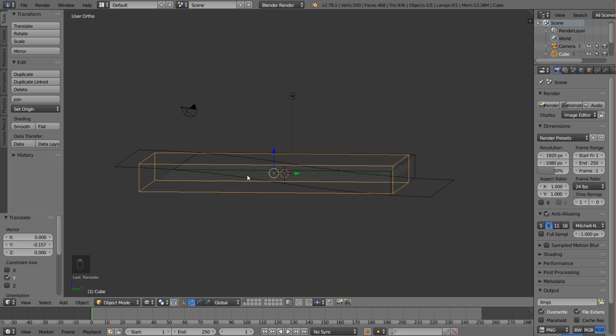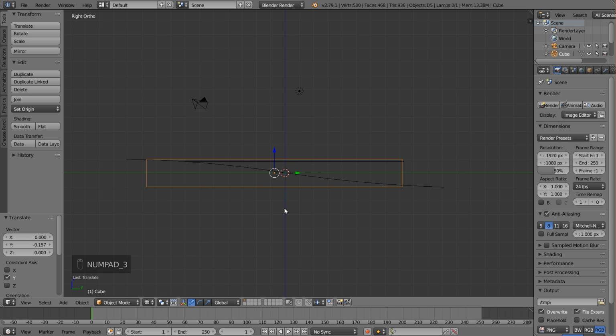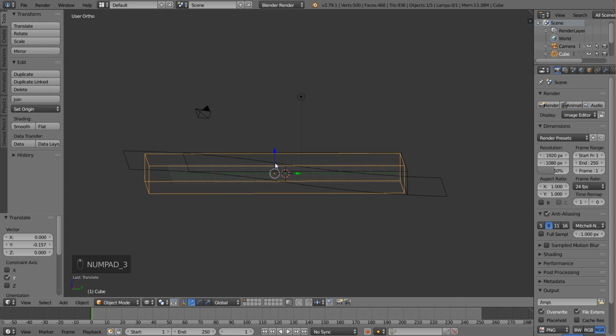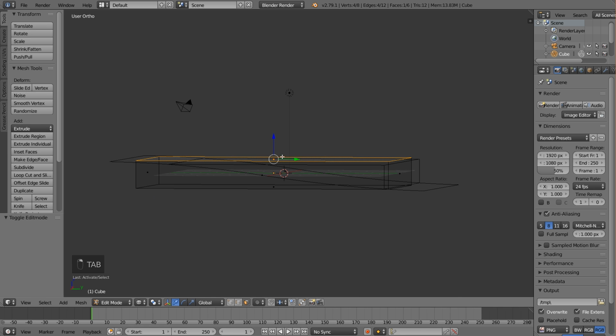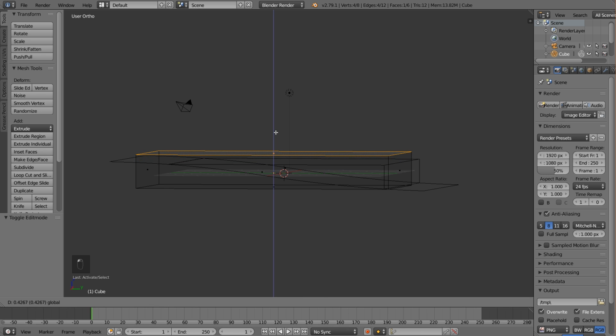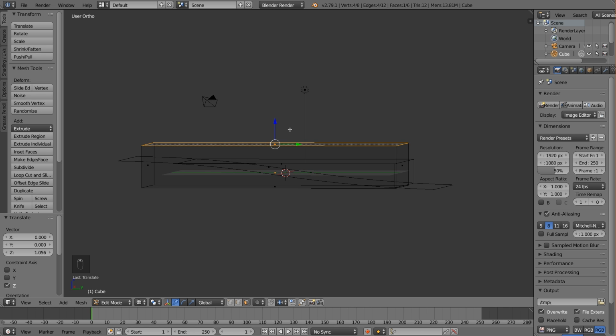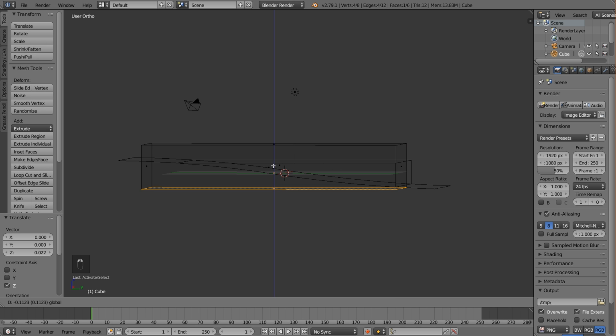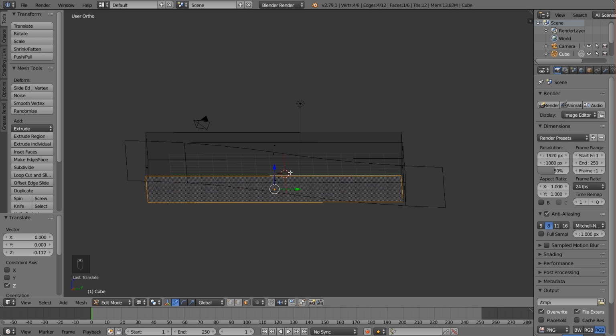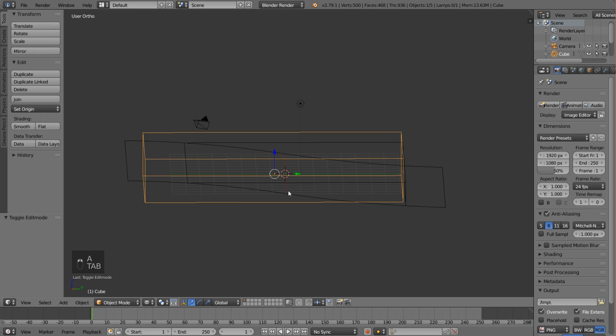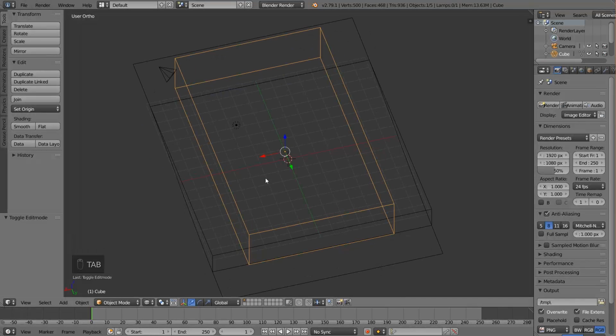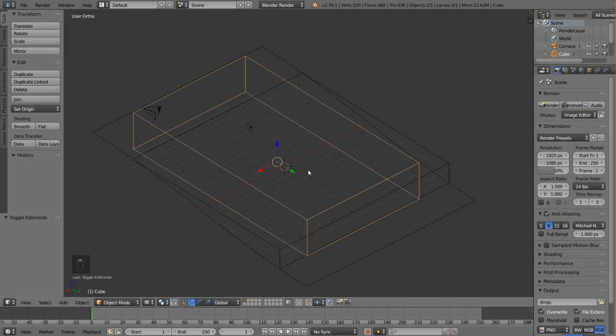And then you want to make sure that there's enough room on top for some waves to come across. So now I'm going to grab that top face and I'm just going to lift it upwards to about there. Something big enough that you can have some waves without it touching the top, messing up your simulation. I'll give it just a little bit more room on bottom as well. And that should be a good amount of room for our fluid simulation.